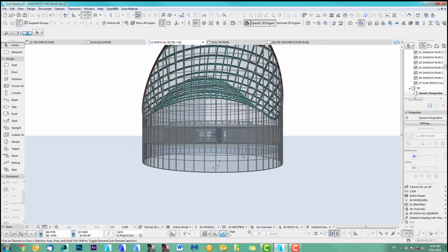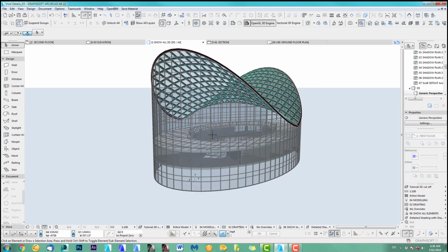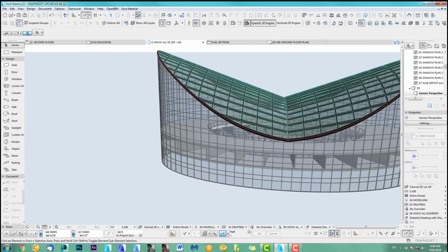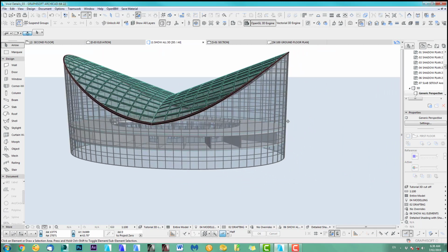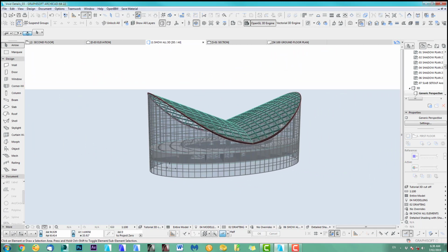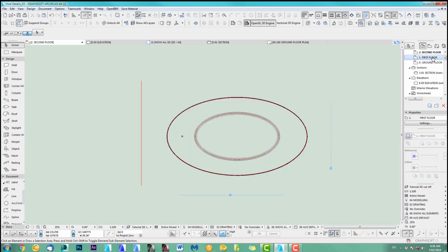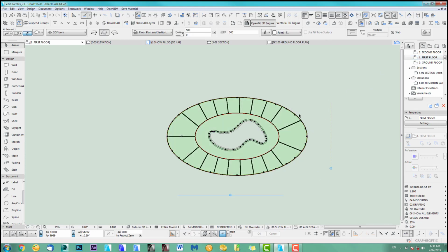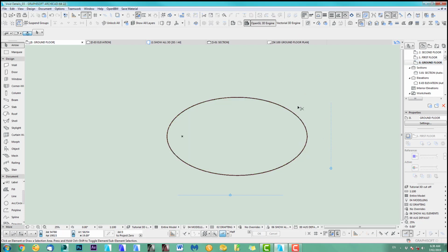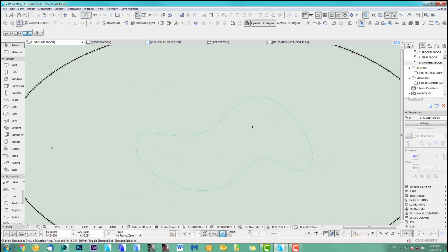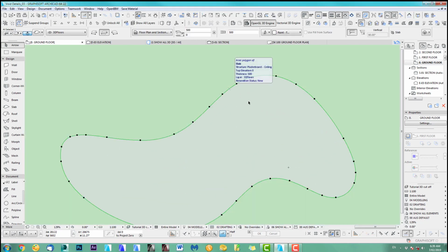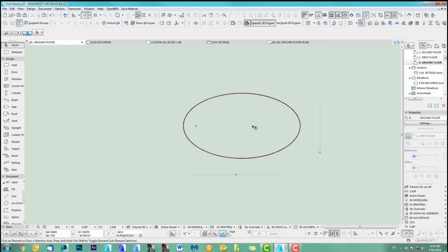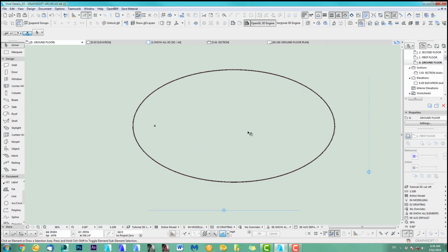So I just add a slab down here and outside some concrete, because it looks a bit too much glass. Okay, so let's do this. First floor, let's pick the slab again, copy, down, paste it in. There we go, we get rid of the hole. And what I like to add is now just some concrete walls around, okay?